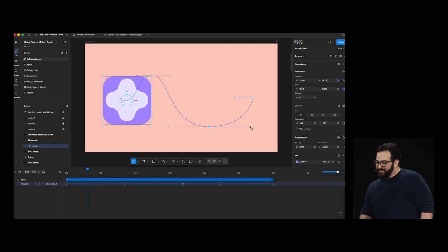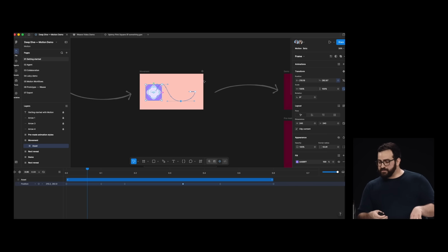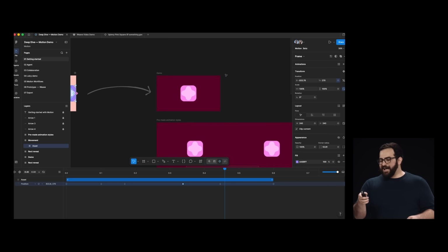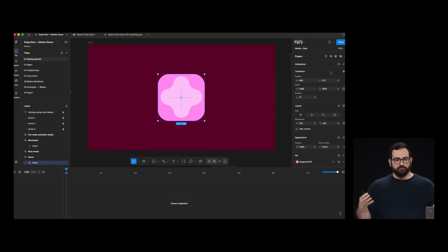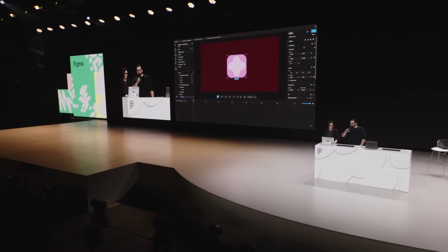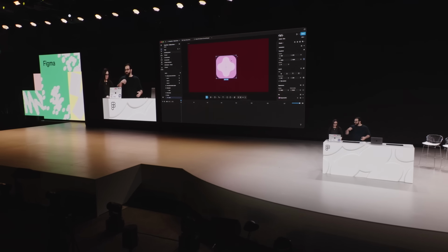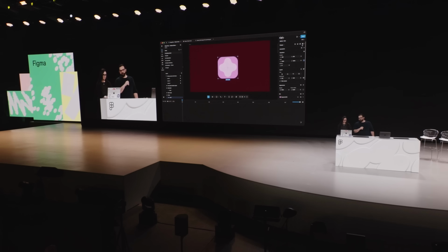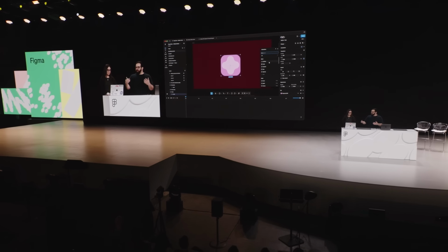Awesome. So this is great. We've shown some pre-made animation styles. We've shown a few keyframes. But let's take a look at some of the library of pre-made animation styles that Figma is going to offer to you starting today. If you select a node that doesn't have any animation, you might not know how to start. Next to that plus button in the animations panel, there's also a little styles dropdown. When you press that, there's a set of pre-composed animation styles.